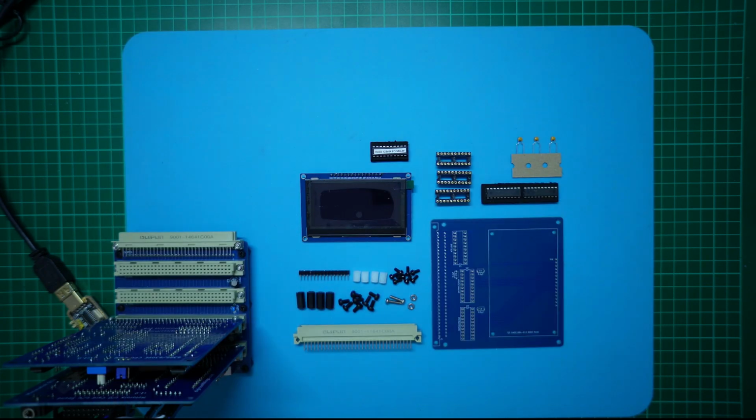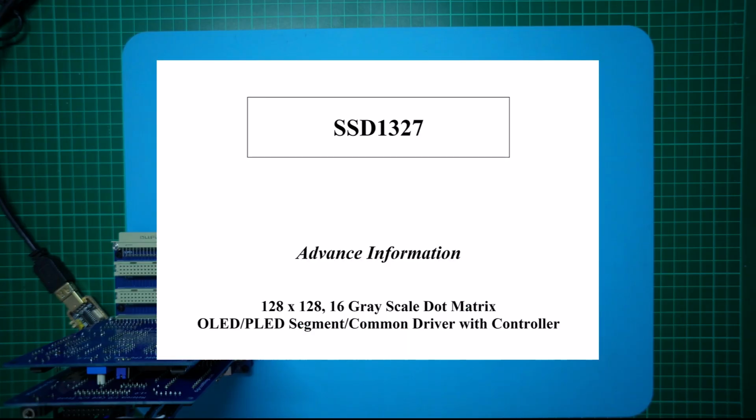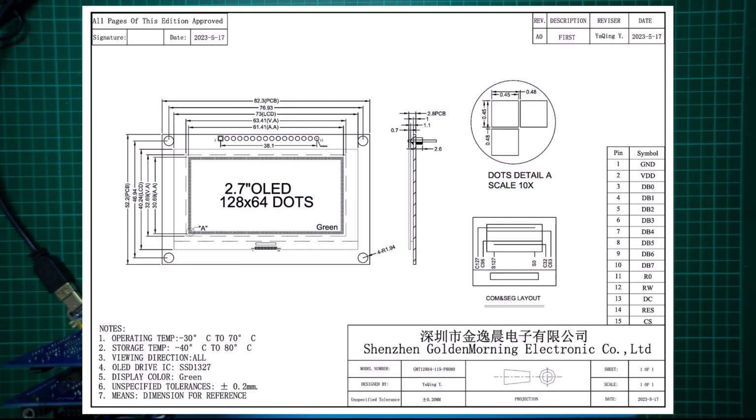Now, I should explain how I got to version 1.2 already. Unfortunately, these display modules don't come with a datasheet. You basically just know the driver IC that the module uses. As mentioned earlier, this module uses a SSD 1327 controller, which the controller's datasheet notes as a 3.3 volt logic level device. The OLED panel's connections are also labelled with VDD for the power connection. Therefore, powering the panel with 3.3 volt power was my assumption.